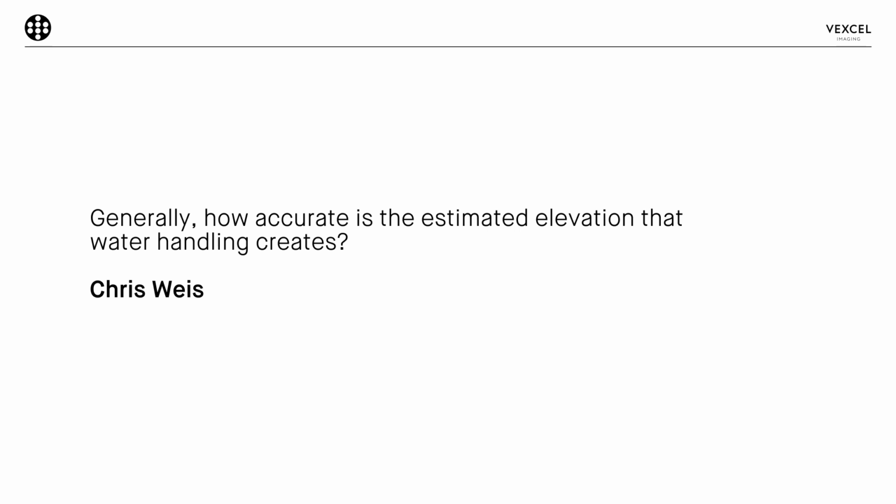So the classification of the water is very successful with detecting the water body reliably. But then at the edge of the water body, the DSM is analyzed. And the DSM in that case gets a lot of height information from the trees and from the bridges. Therefore, the water level is too high in some places.